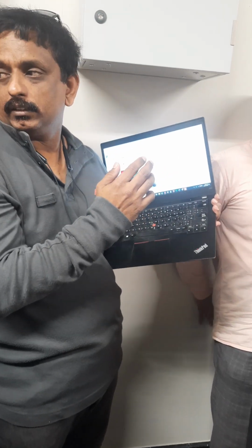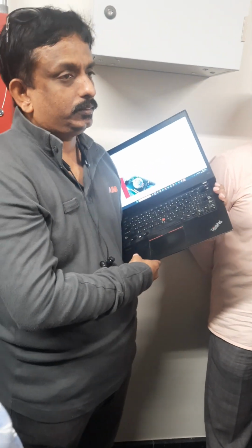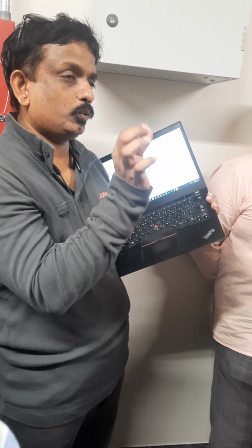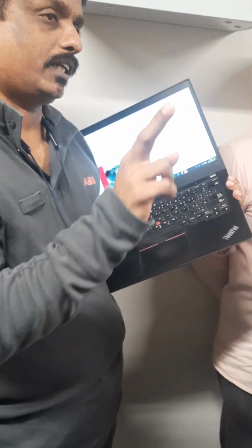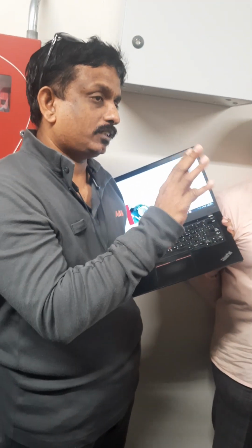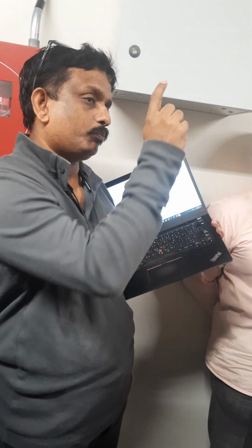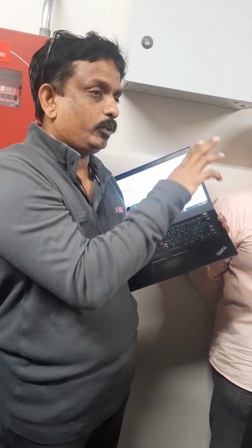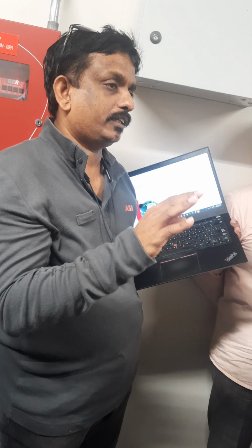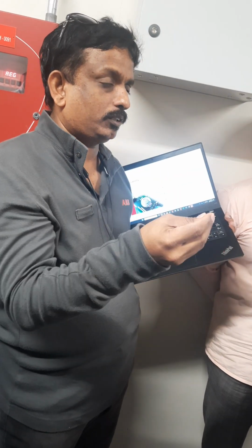There are two relays on the MV switch gear, one chiller trip and the other VFD trip. In that drive there are two kinds of faults, class 1 and class 2. Class 1 means a major fault. It will directly trip the breaker, so the breaker will be open. And class 2 will stop the motor.